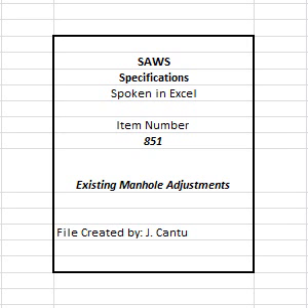851.3 Submittals. Contractor shall submit manufacturer's product data, instructions, recommendations, shop drawings, and certifications. All submittals shall be in accordance with engineer's requirements, and submittals shall be approved by the engineer prior to delivery. 1. Submit proposed methods, equipment, materials, and sequence of operations for sewer construction. 2. Plan operations so as to minimize disruption of utilities to occupied facilities or adjacent property. 3. Submit all test reports and pre- and post-sewer television inspection video. 4. Videos become property of SAWS.